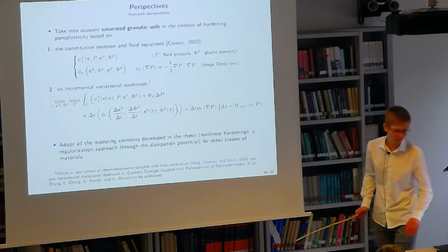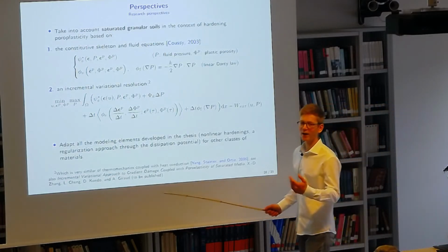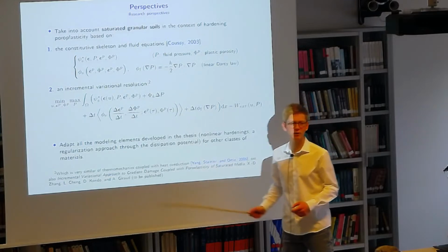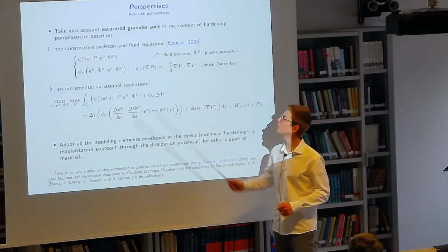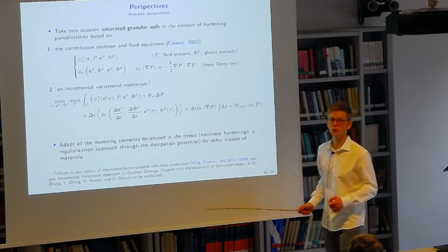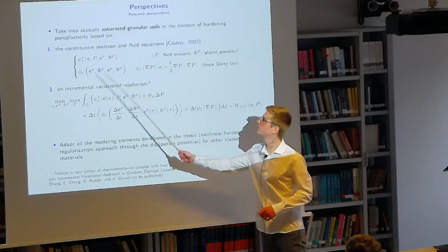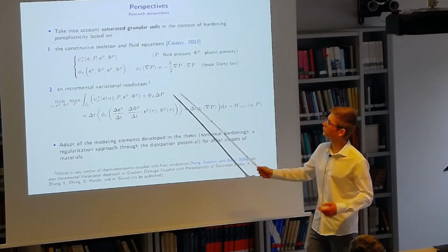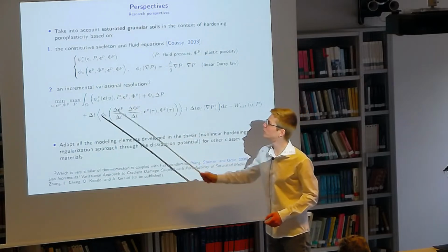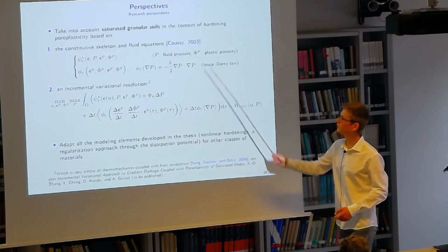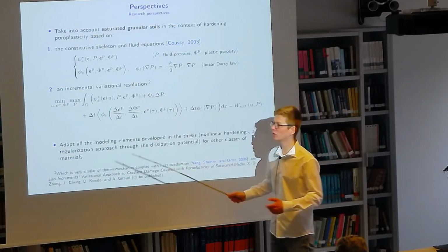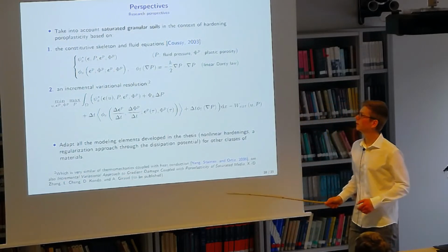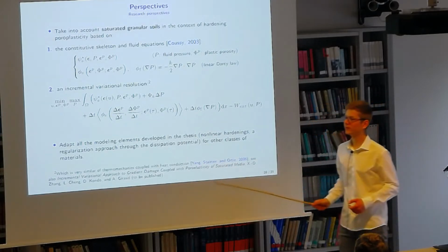a second gradient. As for a research perspective, one of very high interest will be first to formulate the constitutive models in the context of poroplasticity in order to take into account water-saturated granular ones, since so far we have been focused on dry conditions. In this extension, we are going to extend the constitutive equations of the skeleton, taking into account the fluid equations, for instance by extending the dissipation, not just by the skeleton part, but also by the one due to the fluid viscosity. By doing this, we can also rely on a variational resolution which has a lot of similarity with what can be found in thermomechanics, and in particular, we can also design an incremental scheme.